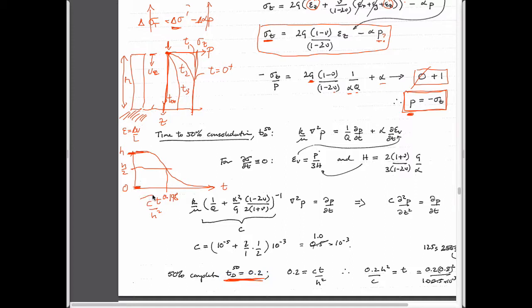And so long as you can define this variable in terms of the appropriate units for this particular expression, this diffusion equation, which is shown here, and essentially, if you like, the magnitude of this C coefficient is about equal to the permeability divided by the dynamic viscosity and multiplied by the bulk stiffness of the fluid or the solid.